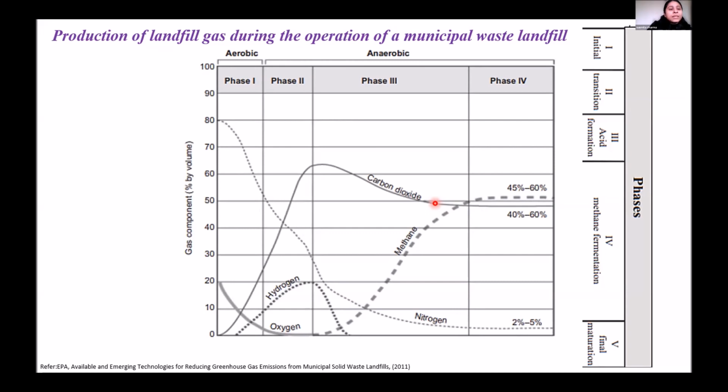with the continuously added and compacted waste, over time the oxygen content of the landfill decreases. This leads to phase 2, the transition state. The decreasing oxygen level leads to less aerobic degradation and more anaerobic conditions being generated. Since this aerobic to anaerobic transition happens, oxygen gets readily displaced by carbon dioxide as an effluent gas in this system. As you can see here, the peaks are increasing for carbon dioxide, so maximum carbon dioxide production happens. Now the third phase.